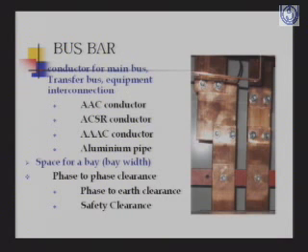We always talk of 33 kV bus and 11 kV bus, where all the incoming feeders are terminated and the outgoing feeders also emanate from a bus. So the bus bar can be of any of these conductors depending on the size and rating of the substation. The size of the bus bar will depend upon the current it has to carry.